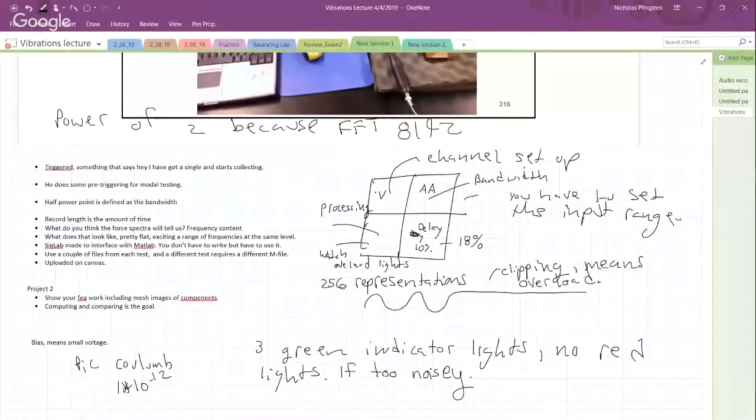So if we just look at channel 2, I'll have better control over it. That's my acceleration response. So that's decaying out. I don't really need any window on that other than if it's always putting the hammer down. So that's the actual acceleration response. I don't remember what this was, but it decays pretty quick. Not a whole lot of it.